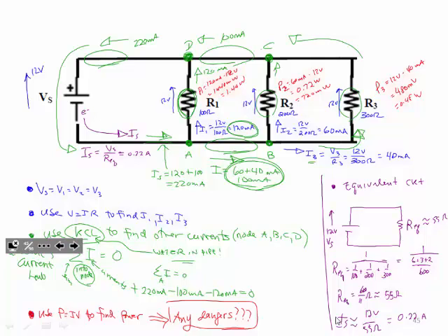So what's wrong with resistors burning? It can't dissipate the heat, so you're destroying your materials, and in worst case, it'll burn through it, or worst case, it starts a fire and melts, and you can injure somebody. So you pick the wrong resistance, or for some reason there's some other error elsewhere in the circuit which is pushing too much current through here, and so you have a flaw someplace else which is overloading someplace else, and you'll get some sort of cascading problem with failures.